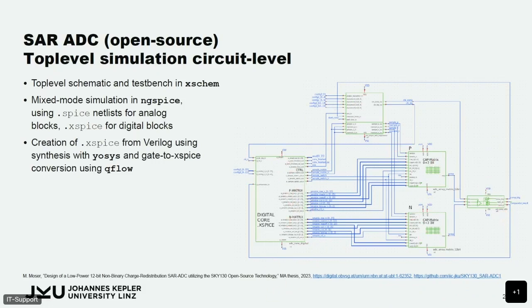And in order to efficiently run this, you need to do this either analog, but this would be way too slow. For pure digital, you have to write very accurate models for the analog blocks, so the way to go usually is a mixed mode simulation. And luckily, Ngspice can do this. So you take your Verilog code, you synthesize it with Yosys, then there's a conversion tool which translates this from a SPICE to an XSPICE format. And so we're using XSPICE inside Ngspice to run a full, true mixed mode simulation. Pretty cool. But this is all on schematic level.